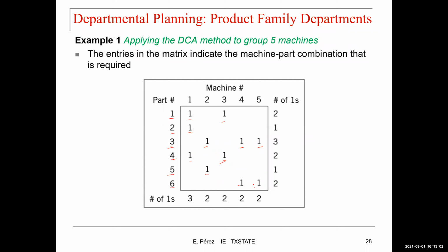So using this information, we want to know how many cells we can build. So we are allocating products to cells. If I end up with 2 cells, I want to say that in this cell, I'm going to manufacture parts 1, 3, and 5. In this other cell, I'm going to manufacture parts 2 and 4. That's the information that I want, because using it, I can design my department and build the number of cells that are needed to manufacture these parts. Okay, so let's try to apply the algorithm.